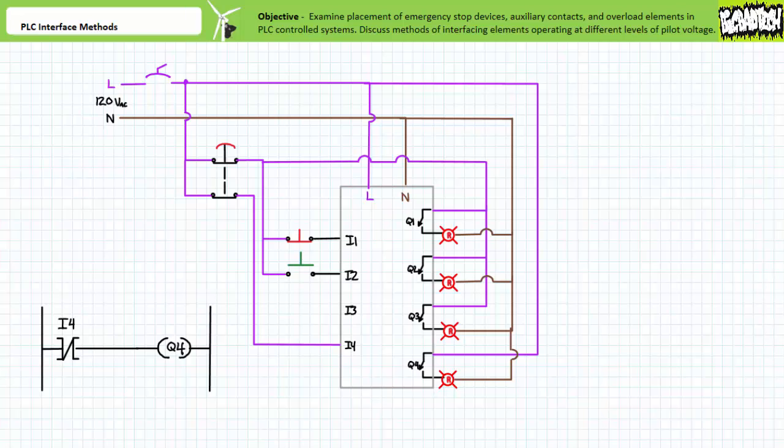Output Q4 is energized, and the fourth pilot lamp turns on. When the e-stop is wired in this fashion, most of the inputs and outputs are still overridden. However, the selectively enabled inputs and outputs still allow the PLC to alert that an emergency stop condition has occurred. Various degrees of this technique could be used to initiate an orderly shutdown of a more complicated system.